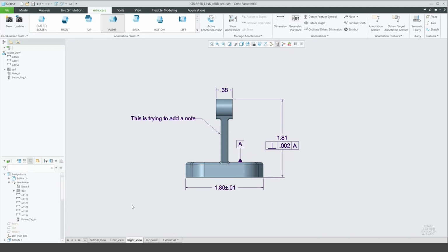The same action will be applied in assembly mode. If you create an assembly file, you can similarly go to annotate and then use new to create a tab, and then rename the tab, then add the dimensions, add the geometry tolerances, etc. So all the steps that I show you here apply exactly the same in your assembly mode as well. Okay, so this is the first part.